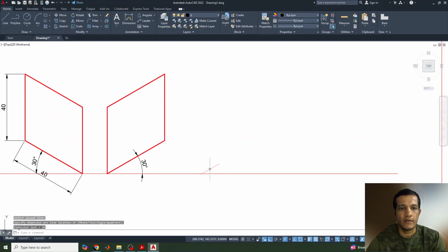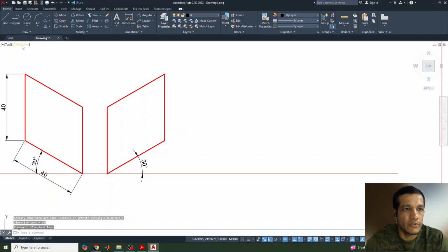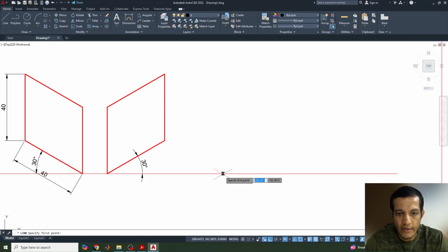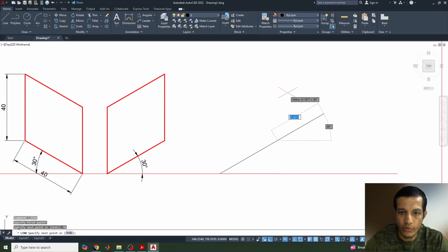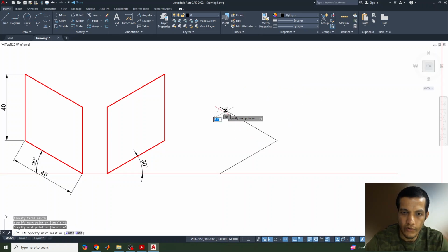Similarly, the next option is top. I can select isoplane top again here, or I can just click F5. So that can also be done. Similarly, we'll take one point here and go this side, we know that is 40. Only the top side will be moved; it won't go left and right. It will just move on the top. So again 40.